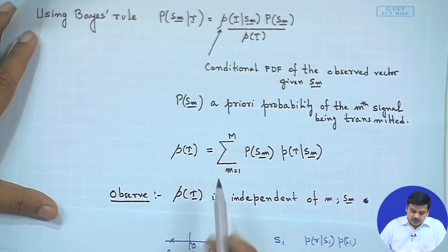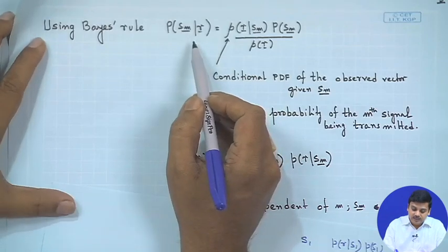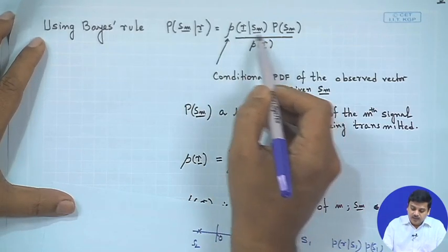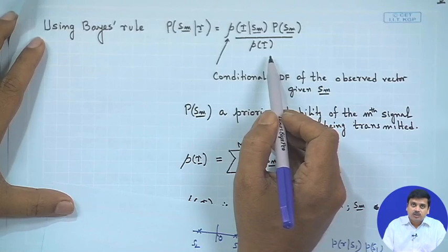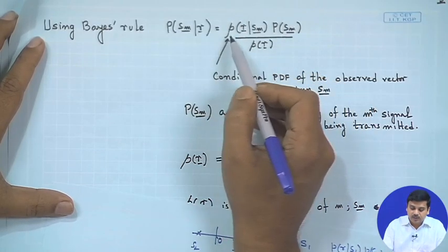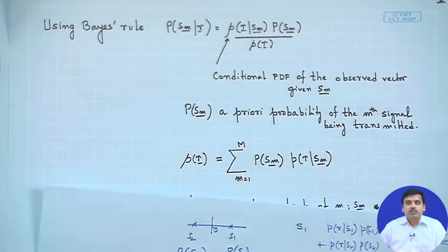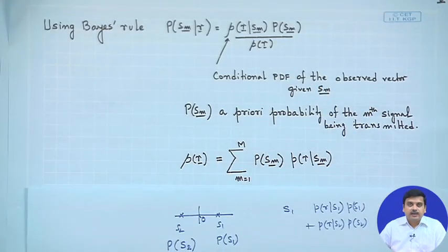So, if we have to maximize this probability, we can see that the denominator term is almost irrelevant for us. All we are left with is the numerator term. A similar situation we had when we discussed the properties of the matched filter, where we found that if we could hold the denominator constant, we could maximize the signal to noise ratio at the output by maximizing the numerator.